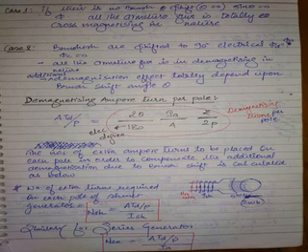Next, ampere. Let us say IA is the armature current. Then, what is the current flowing in the armature conductors? It should be IA by A. If you say this is the armature and this is IA, generally the current out of the armature is IA. So in the armature there is winding. In the winding there are parallel paths, at least 2 or 4 or 6 parallel paths. So when you have 2 parallel paths, I am representing like this. The winding is in 2 parallel paths.